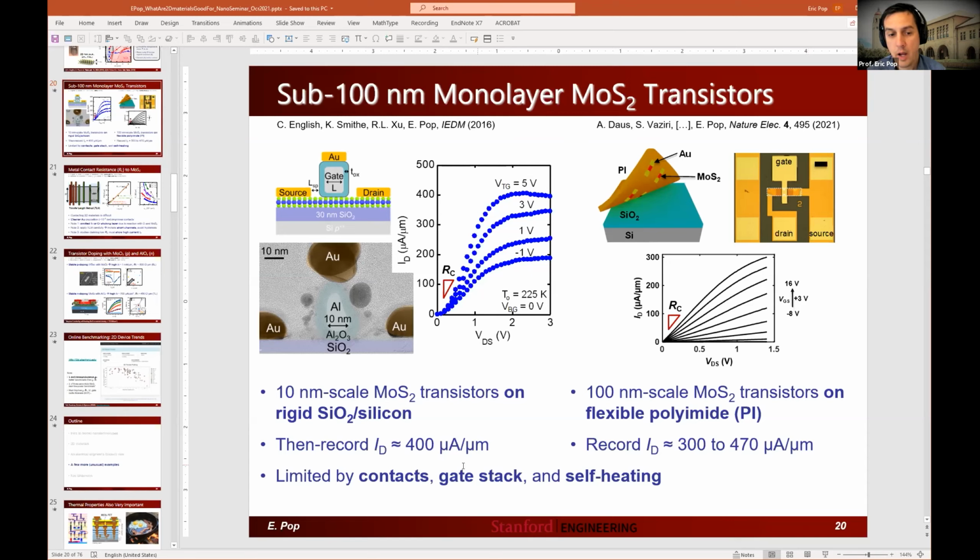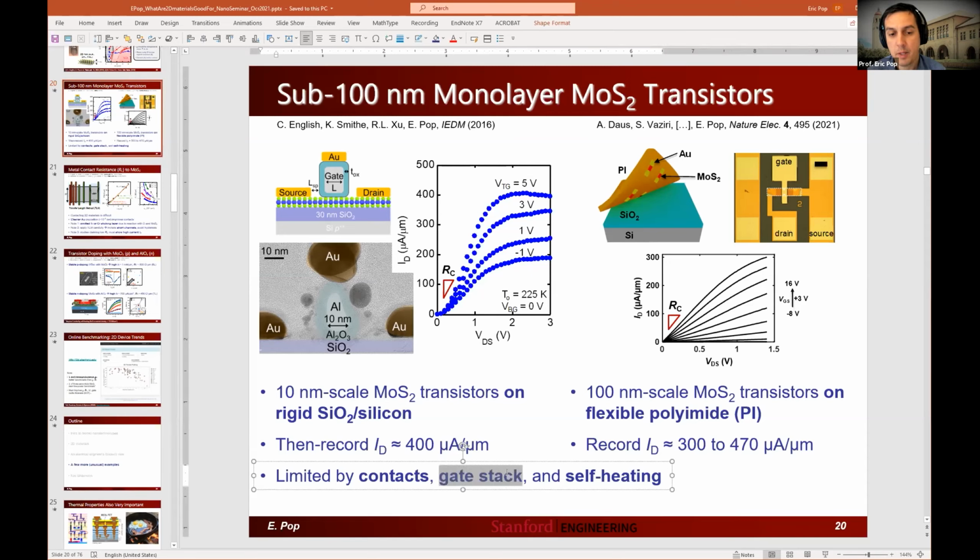And so that's why I wrote here at the bottom that the gate stack, meaning the gate dielectrics, absolutely have to be reduced in thickness, because right now our gate switching voltages are not low enough, and they must be below 1 volt. And then, yes, we will be able to get there. But the metric, just to be clear, is high current at low voltage for anything that has to be low power and compete for low power applications.